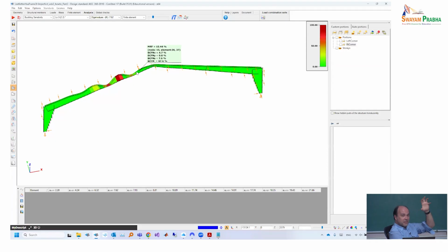Deformation energy is stiffness multiplied by displacement squared, and multiplied by 0.5. This is the same type of energy as movement energy or spring energy, and any type of energy is calculated this way.